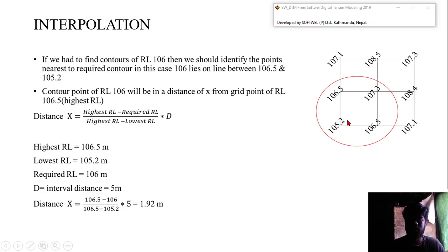So we are calculating manually here. We consider every grid line connecting each pair of grid points, and then we run calculations for each line. Then after that we mark the point, then connect the points. That is called a contour. To mark that point, we just need to interpolate. So the interpolation goes like this.